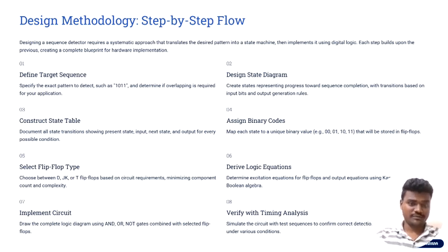Construct a state table. Document all state transitions, showing present state, input, next state and output for every transition. Assign binary codes and map each state to a unique binary value that will be stored in flip-flops. Select a flip-flop type. Choose between D, J-K or T flip-flops based on circuit requirements and managing components and